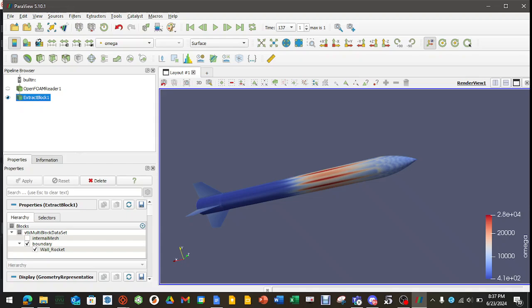Go through the technical report, write down the equations, do things, go through the appendix number 1, and print off the report, or at least the graphs that you need for the appendix 1 exercise. Go through it, learn how to use those Reynolds number tables, and find the drag of your rocket from the very beginning to the end. Just pick a model rocket and find it. I did it for this rocket for a master's project, and it was really cool, and I got within like 1 decimal place of OpenRocket. It was amazing how cool it was.